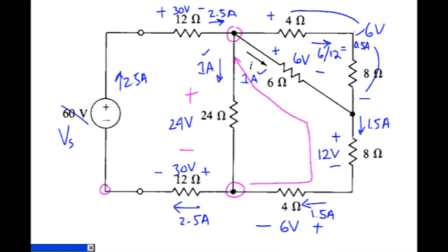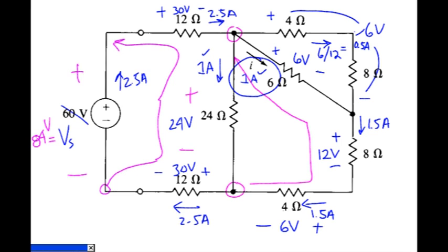And I'll do the same thing we did earlier to get the voltage across the source. We have a voltage rise of 30, another of 24, and one more of 30, leading to a voltage, and Vs equals 84 volts. So we assumed an output, this is my proportionality factor, we assumed an output of 1 amp and determined that that's produced by a voltage of 84 volts.